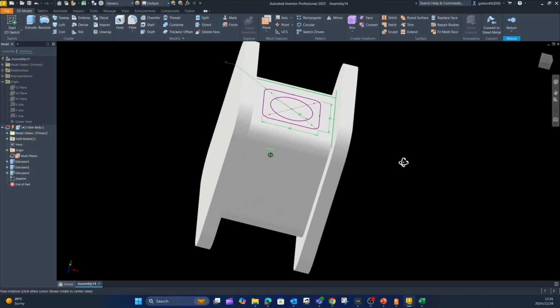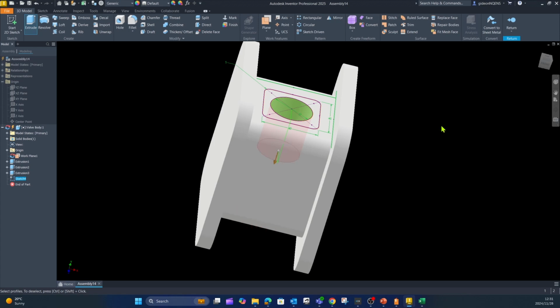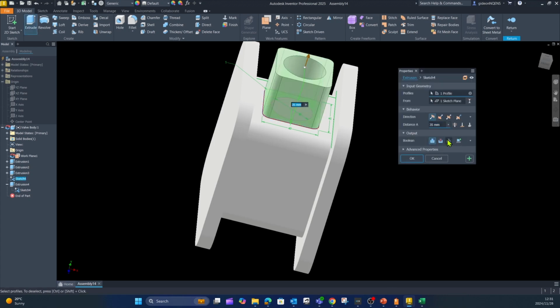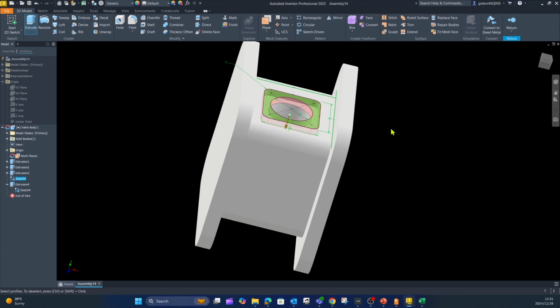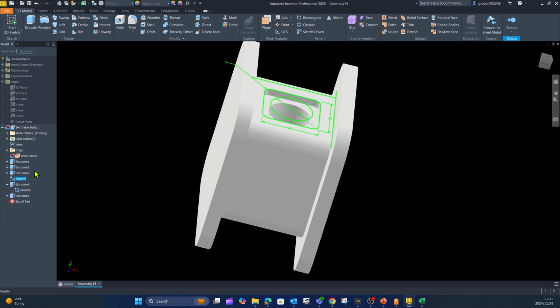Finish it, use the extrude just to cut that completely through. And I'm going to say, let's say that is 35 deep, just as an example, not 350, just there we go. I'm going to share this sketch and utilize the extrude and cut that, let's say 5 millimeters, just to create that depth. From here I can switch off the visibility of that specific sketch.